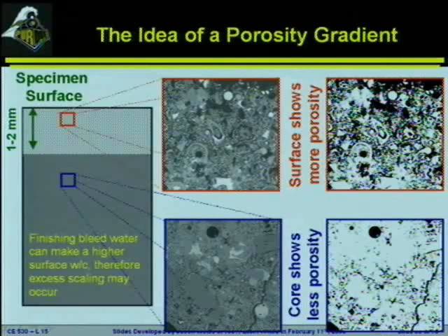of the concrete. One of the things that we noticed, and one of the reasons why this is particularly problematic when we start talking about supplemental materials, is the fact that your surface is not going to be as dense as the rest of the concrete. And we'll talk about this later when we start to talk about the concept of bleeding, but essentially your fly ash particles are fairly light, want to float. Your slag particles are a little bit light, and what you will see if you take a scanning electron microscope image, you will see that inside of the core of the concrete it tends to be much more dense. Toward the top surface, the system doesn't necessarily get as dense and there's a lot of holes or porosity.